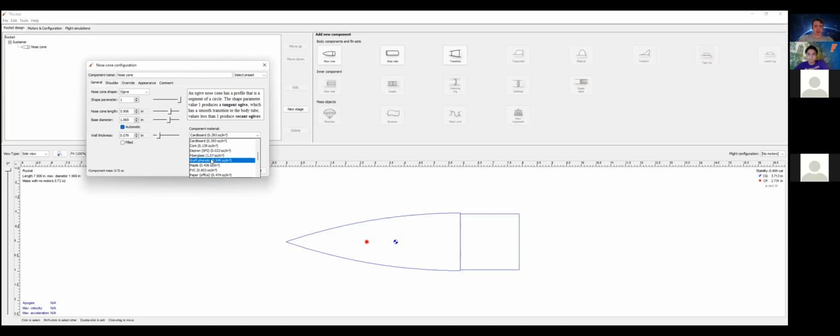Yeah, so just a heads up on all of these material selections, and he's clicking around on all of these numbers over here. One of the big problems that happens when anyone does their first design on OpenRocket is they do non-standard sizes for all these things. They're like, oh yeah, my nose cone will be 6 inches long and it'll be 5 inches thick. Well, 5 inches, no, but you get the idea. Basically, make sure that when you're picking these sizes, you're using actual material we have. If you're off on something like wall thickness, even by just a little bit, you can throw your rocket off weight-wise by a lot.